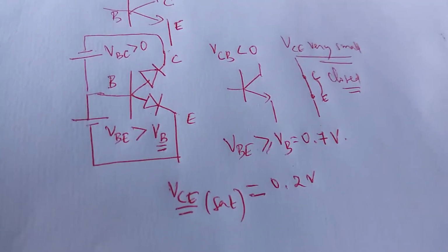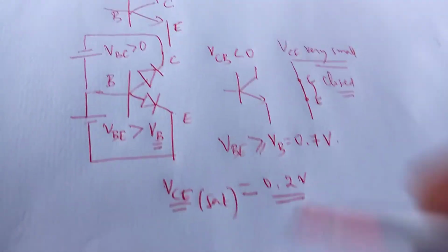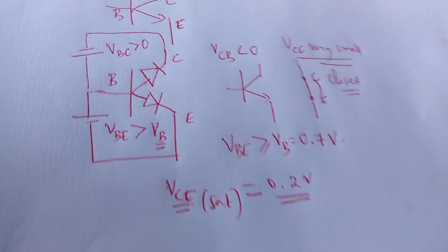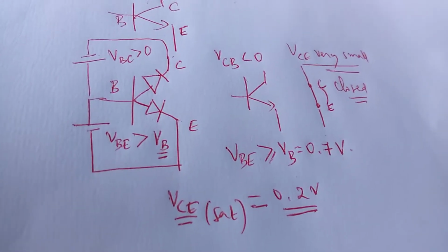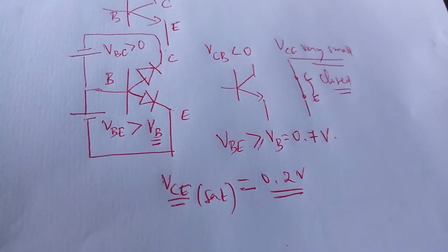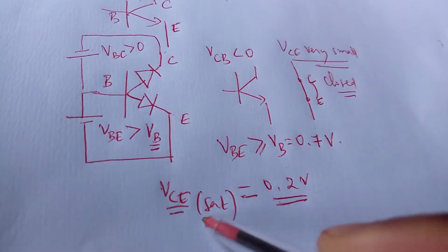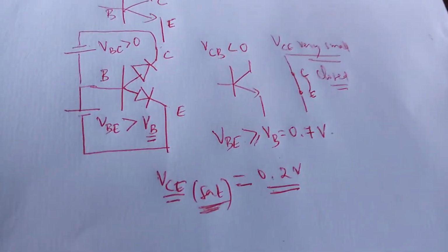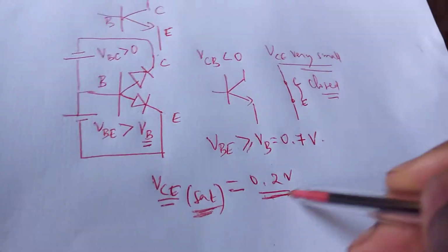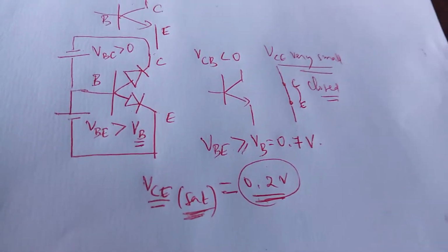Normally, when you read the datasheet of a specific NPN or PNP transistor, you should be able to get the predefined VCE under saturation value, assessed in the lab. The key thing is to know that it's very small. We'll work with VCE at the edge of saturation, meaning when the transistor is about to go into saturation, at 0.2 volt, and that's what we're going to be working with to say that the transistor is in saturation.